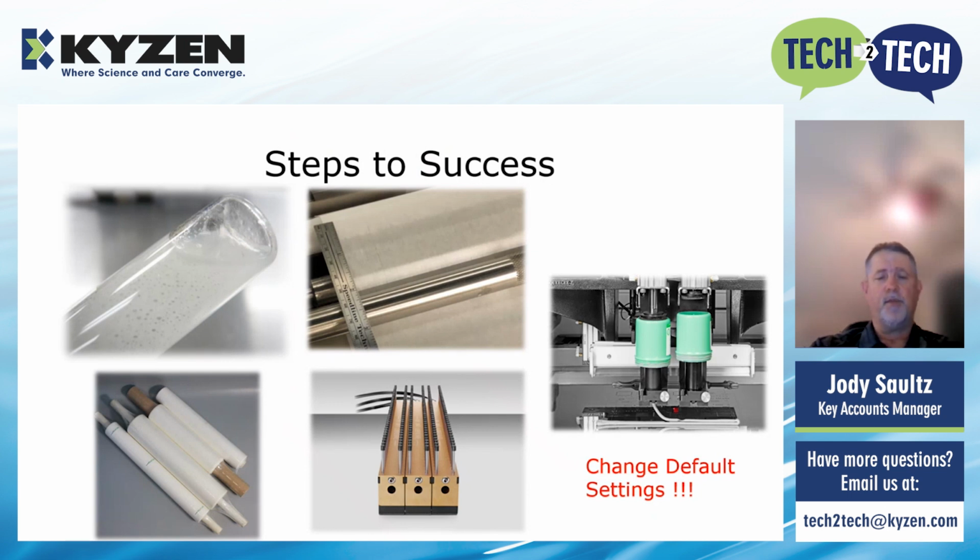But if you optimize the whole printing process, right chemistry, delivery system, the paper, and of course all the tooling as far as board supports go, and making sure that you're delivering the right amount of solder paste to the stencil so you can get proper print process across the stencil. Even if you're doing it manually, you still have to make sure that you're putting the right amount of paste per se on top of the stencil.